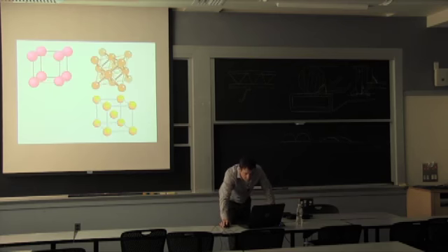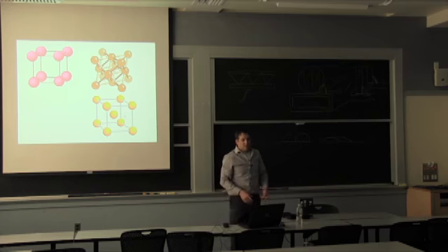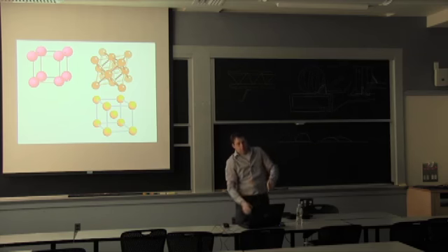So what happens when you quench, and that's something that I want to get into the details right now, is you go from, instead of going from this phase to this one, you go to another phase that's called martensite. It's not a cubic. It's very close to a cubic. It's a tetragonal phase. So think of it as this one, except that it's stretched a little bit.